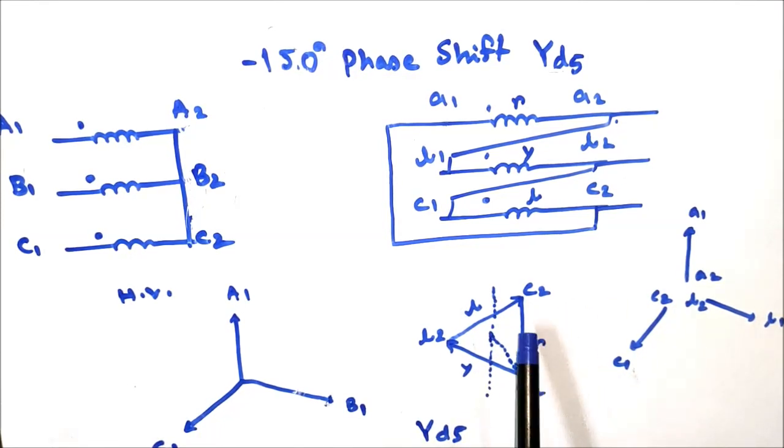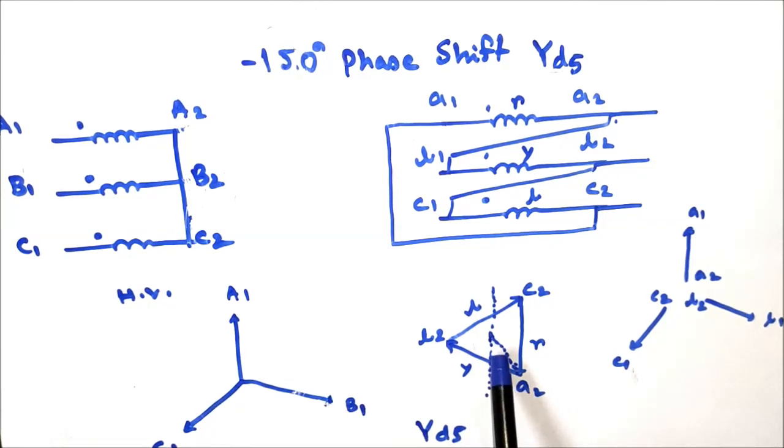So if I draw the virtual neutral and extend it towards the connection terminal, that is the red phase A2, and the virtual neutral is extended to the vertical line that represents the 0 o'clock, and further extended downwards, it will represent the 6 o'clock, and it will be minus 150 degree phase shift from 0 o'clock, or in clock rotation it will be 5 o'clock.